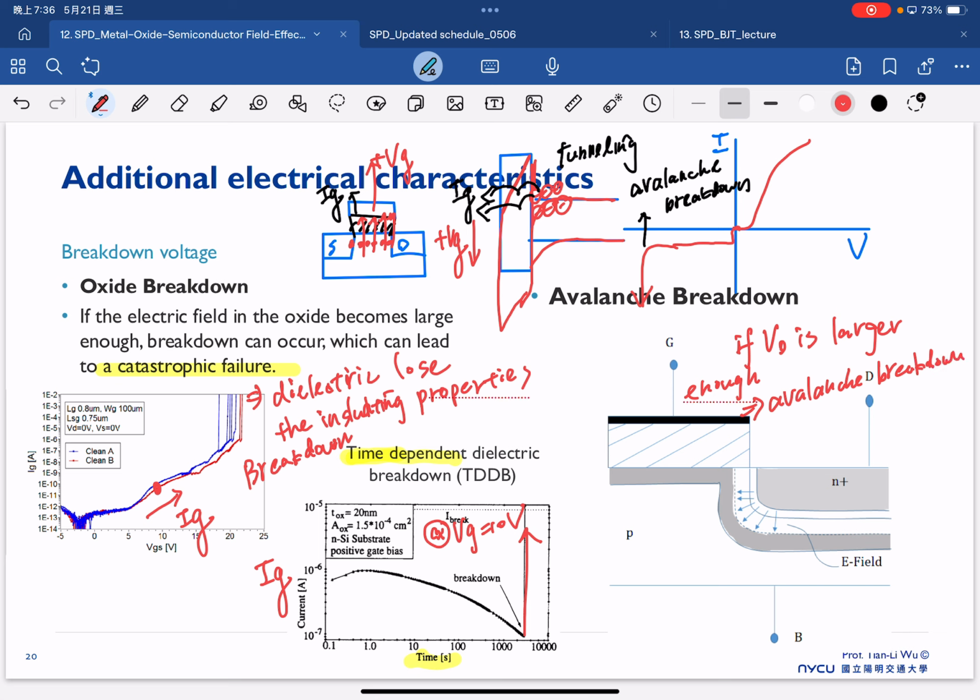And this is because it is a reverse PN junction. So considering the reverse PN junction in the drain side, if you try to plot the ID-VD, in the beginning we should have a very low current. This is the case of VG equal to 0 volt.